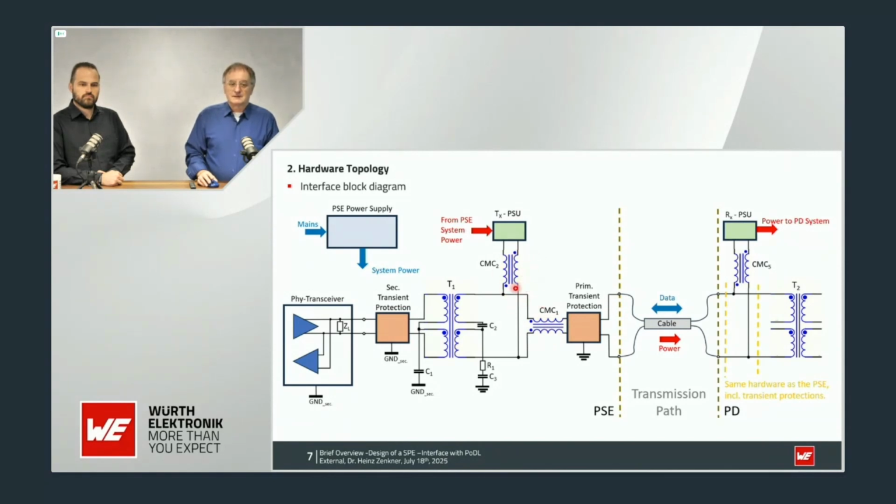But you see, that's a common mode choke which is used vice versa. So we have here the dot, and at another line, we have the dot on the top. The idea is to decouple the signal, because the signal is in differential mode. So we decouple the signal and incouple the energy going to the powered device. And we have a transformer. This is the huge difference here.